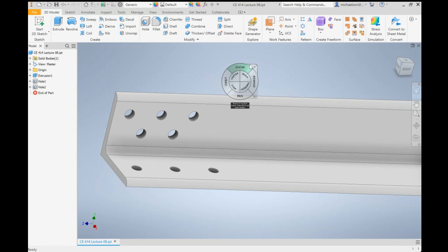Then what you have to do is draw all of the possible failure paths that leave those bolts intact. It wasn't me looking at it and just saying, well, it's going to be this and this. You have to look at the connection and identify all of the possible ones that keep those bolts intact.